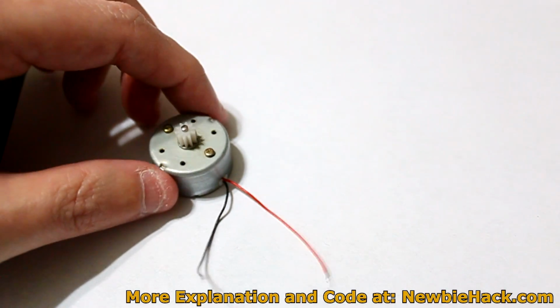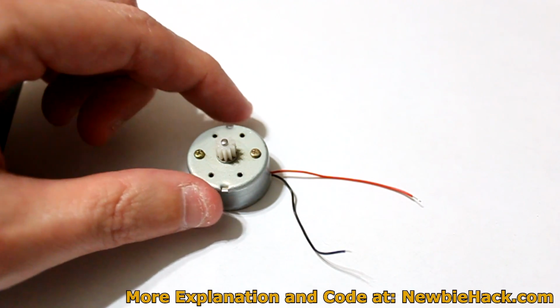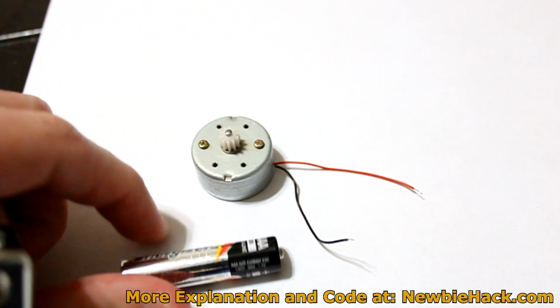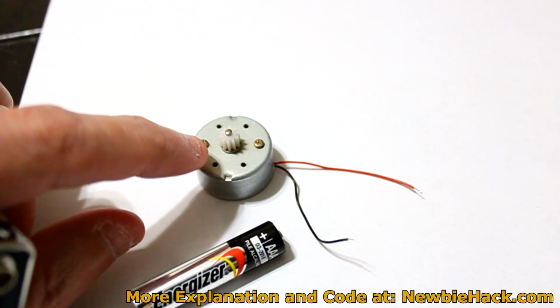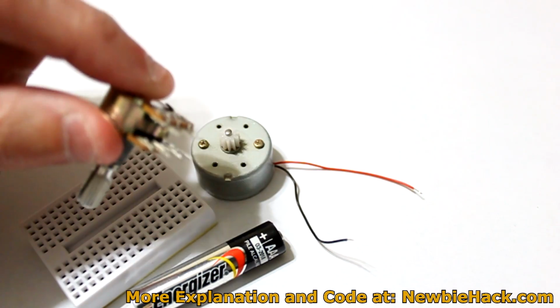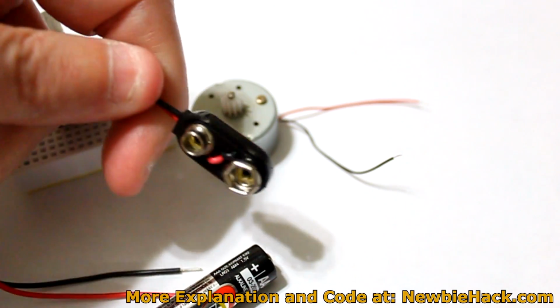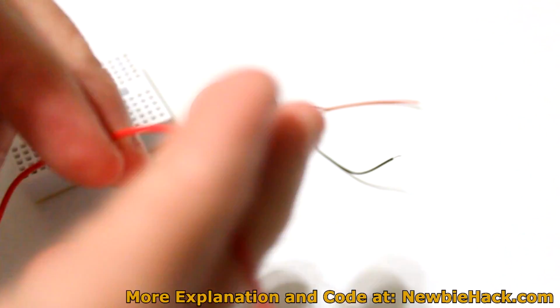Let's go one step further and create a circuit that provides any voltages between 0 and whatever battery we'll be using, either the 9 volt or the 1.5. And we're going to connect it to a potentiometer so we can adjust the voltage going to the motor, and we'll see exactly what can be done with analog voltages and controlling a motor. I'm going to use a small breadboard and a potentiometer, as we did in the previous videos. I'm going to use one of these handy connectors for the 9 volt battery. And you want to try not to allow the two ends to touch, because that would be shorting the battery.